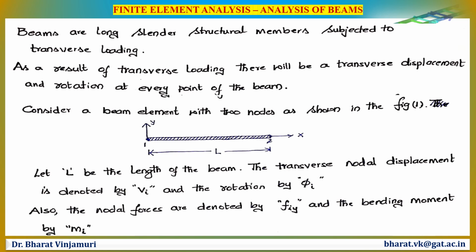So what exactly are beams? Beams are structural members that can take transverse loads. Unlike bars, which can take only axial loads, beams can handle shear force as well as bending moments. As a result, there will be transverse displacements and rotation, or here we call it slope, at every point of the beam. Here the figure shows a beam of length L in global coordinate system.